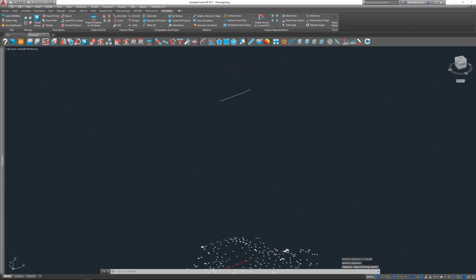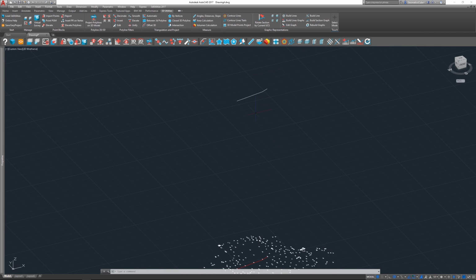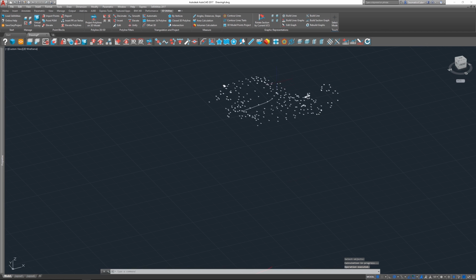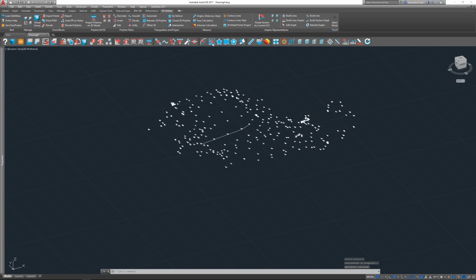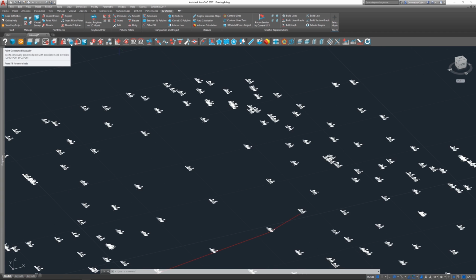As you can see, another 3D polyline was created, and this time it's in 3D because it has the elevations of the 5 points that I've used to create the polyline itself. And I can do the same thing for the points. Using elevate point blocks, I can elevate all these points, so I select them all. Now they have the correct elevation, and I can do an automatic triangulation just like this. So I already have a 3D model.